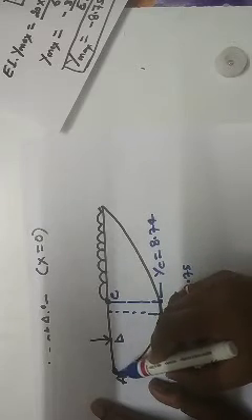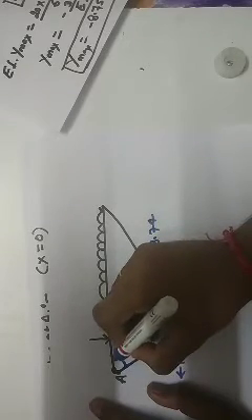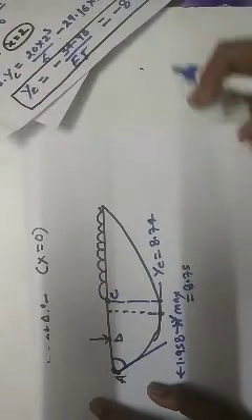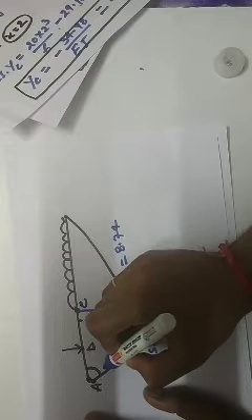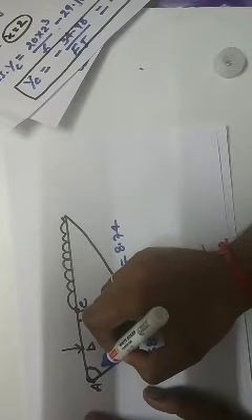Now we have calculated the slope, right? Here we will draw a tangent. This is our tangent, and this angle we have calculated, this angle is 0.417 degree at end A. Why is it minus? Because it is measured in clockwise direction, so this value is negative, and this is equal to 0.417 degree, right? So this is the calculation that we have done.